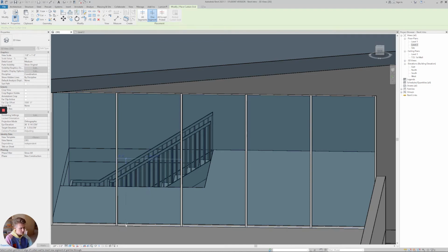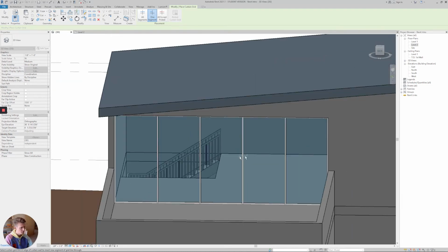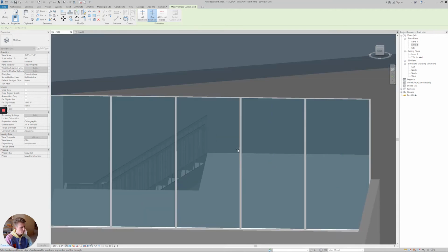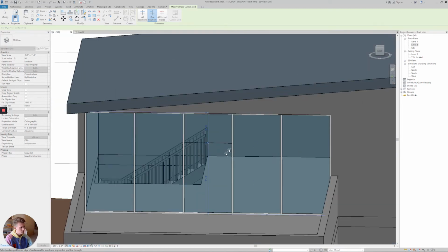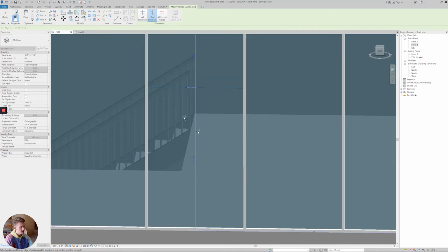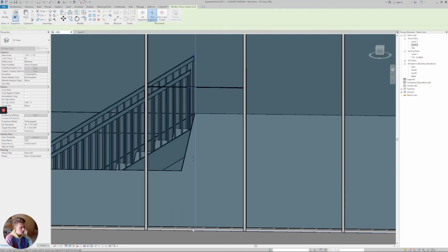So I'm going to want to make this about 7 feet off the ground here on probably this central panel here. So I'll select here and find until that bottom measurement is about 7 feet up. It's right there, and it adds the grid line for me. But this is still too wide, so I'm going to do the same thing, except now to add a vertical grid, I'm going to mouse along this bottom piece here.